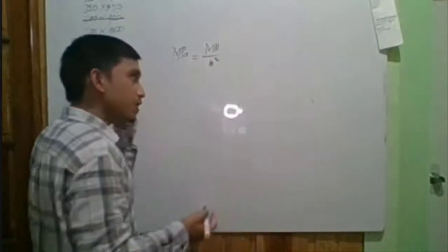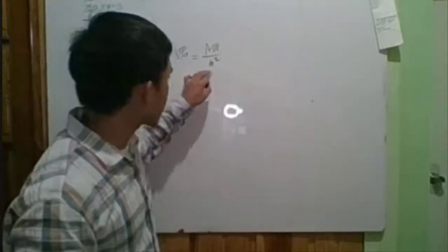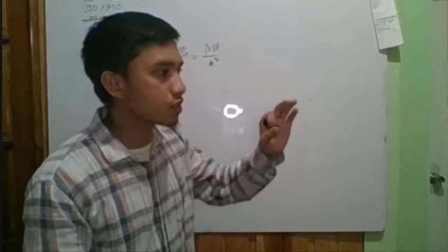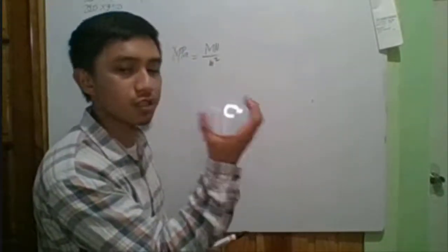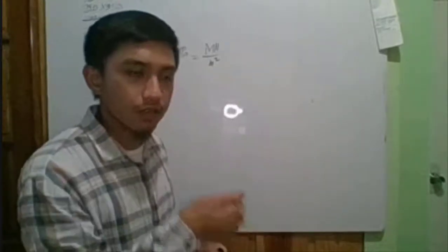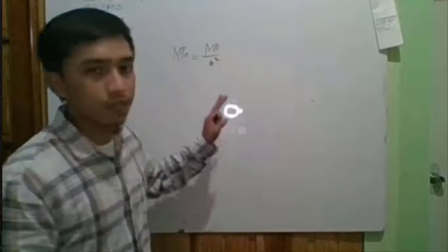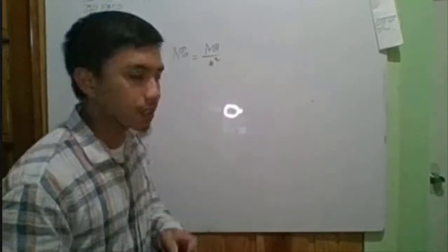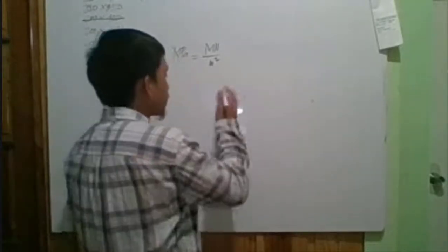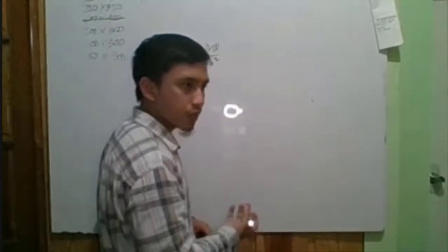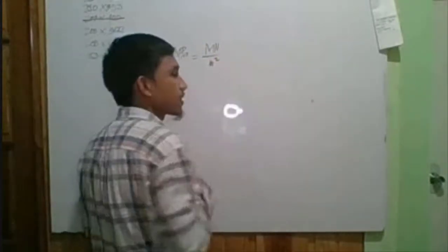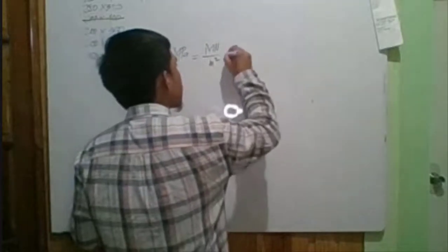But later on, if this is what you will be using, you will end up with an area in meter squared, which is a very, very small number. Why? Because we are considering a steel tube that is that small. So it is better if you express that in millimeter. And the millimeter always goes with Newton, not meganewton, because meganewton per mm squared will also be a very, very small number. So we need to convert this in millimeters and Newton.